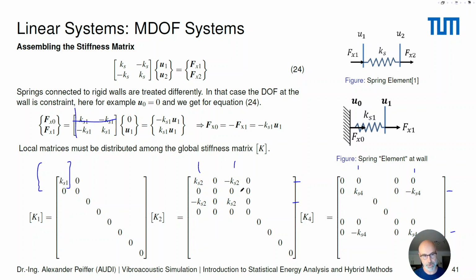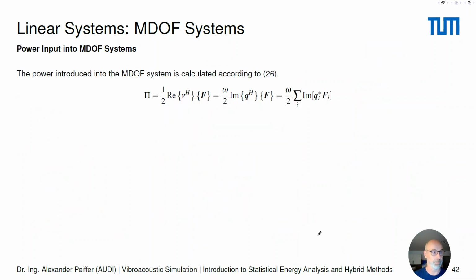So all the nodes that you will find in the global mesh of the finite element program, they calculate the mass matrices and they calculate the stiffness matrices using a specific algorithm, which could be super complicated. Again, this is not a lecture about finite element methods, but it's very important to understand the global concept of mass and stiffness matrices in a dynamic system. And this is the concept here.